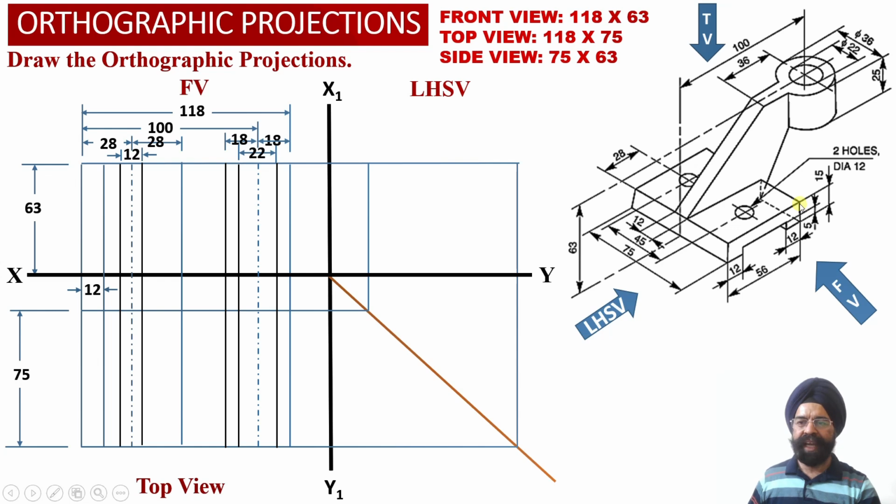Similarly, from the right hand side face of this element number 1, we have a vertical leg over here, and this distance is equal to 12 millimeter once again. So from this extreme point of the horizontal web, we again take a distance of 12 millimeter onto the left hand side, corresponding to this vertical edge of the second leg of the horizontal web, corresponding to this rectangular slot.